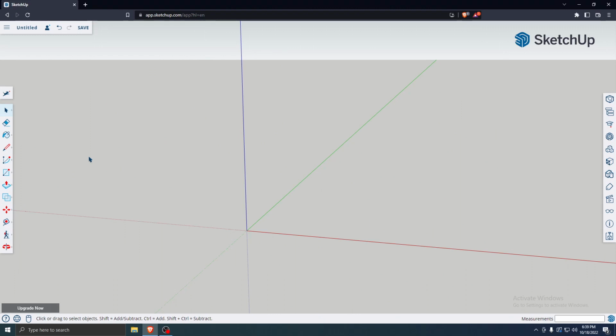So let's start by making a basic shape like a wheel. Before you make a 3D object, you have to make a 2D drawing. So hit the C on your keyboard, and you'll see a pen and a circle appear where your pointer was. If you ever want to go back to the select tool, which is what we used to select the SketchUp Dude, just hit the spacebar. For now, we're going to keep it on C for circle.